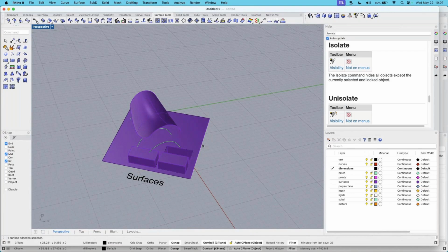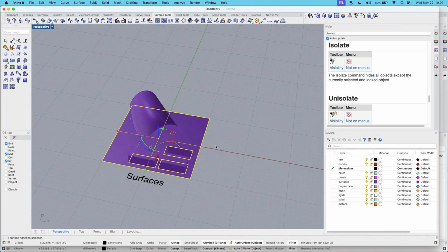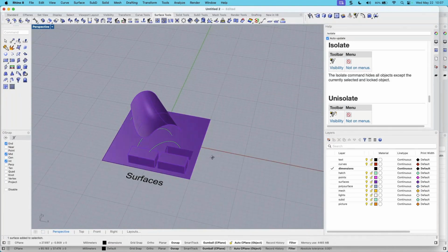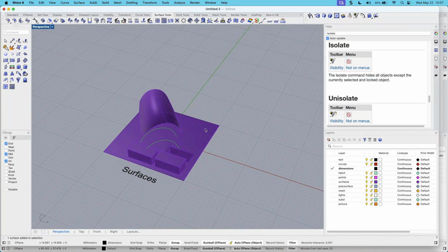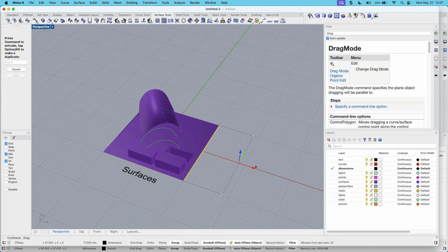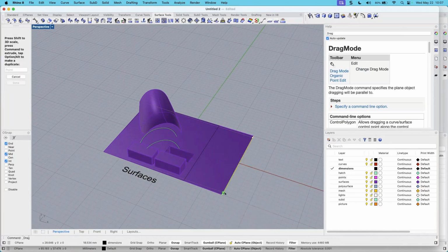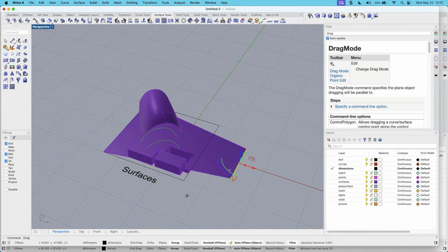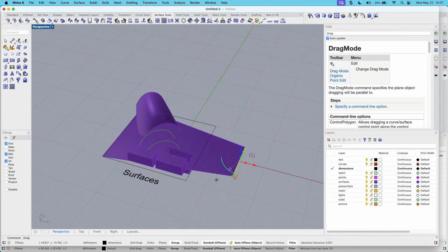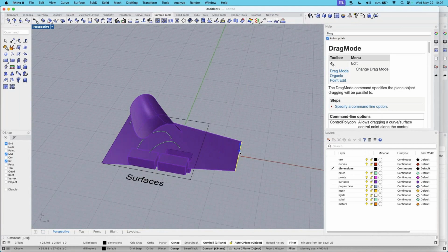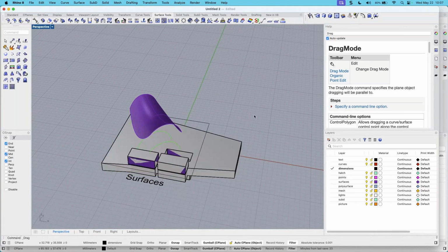That is a poly surface now, so it is giving us a little bit of issue with picking that. There we go. That's what I want. I want that edge. I can pull it out. I can shrink it. So anyway, a little bit of editing, whatever your editing is, maybe you'll extrude that curve or maybe you'll extrude the entire surface.